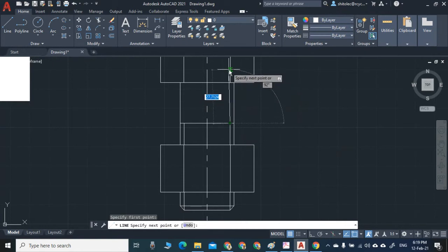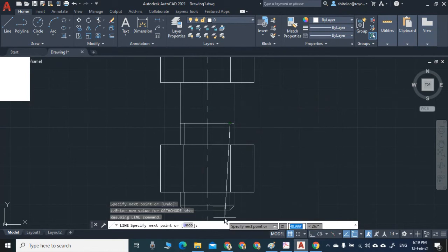This is 30 degrees with vertical, like this, means this angle is 60. Yeah, Hannah, you can click it here, or give the command at the rate shift to at the rate 10 angle 45. Sorry, 60. 30 with vertical means horizontal 60. Enter.